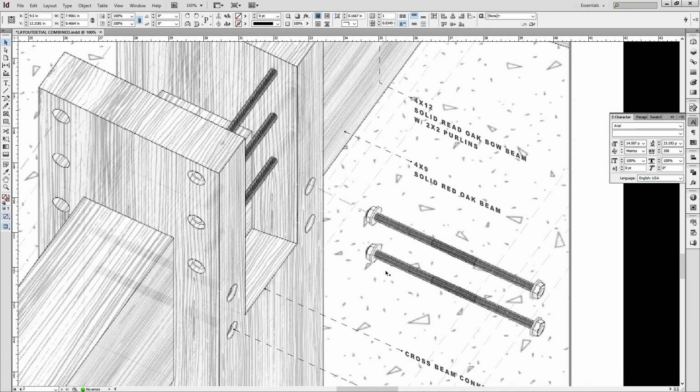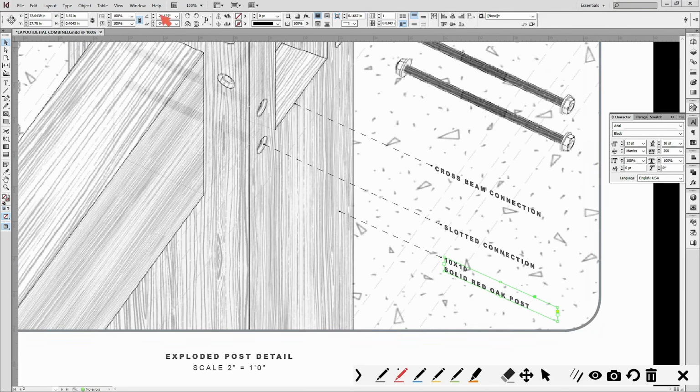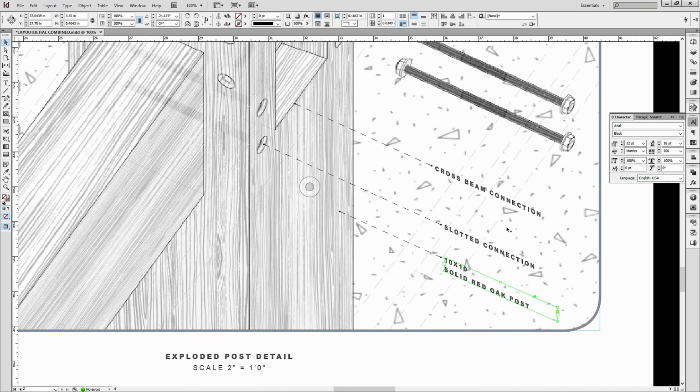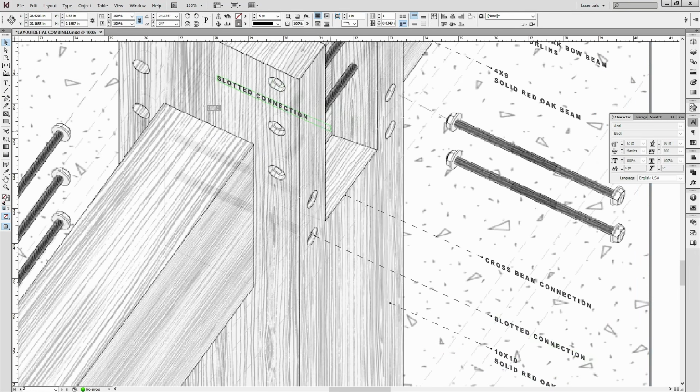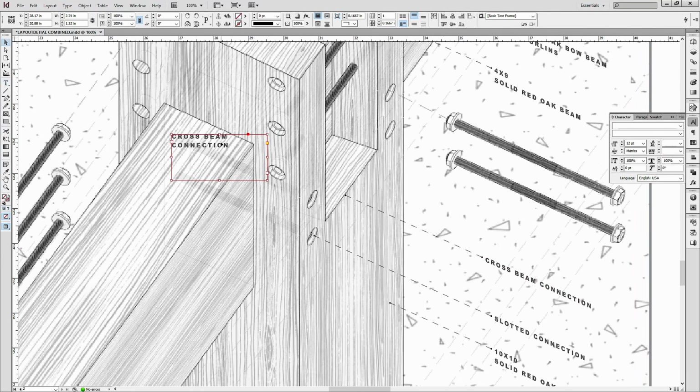But on my labels here, you see, I have this going in the same orientation as my Axonometric. And the way that I do that is, if you see up here, let me show you, I have my shear angle and my rotation angle the same, okay? So on your text, you'll take your regular text and rotate it until it lines up to this actual text. So let me just do a test so you understand. Let me copy this text, make a new text here and just paste it, okay? So let's say we have this text here, right? Like this, okay?